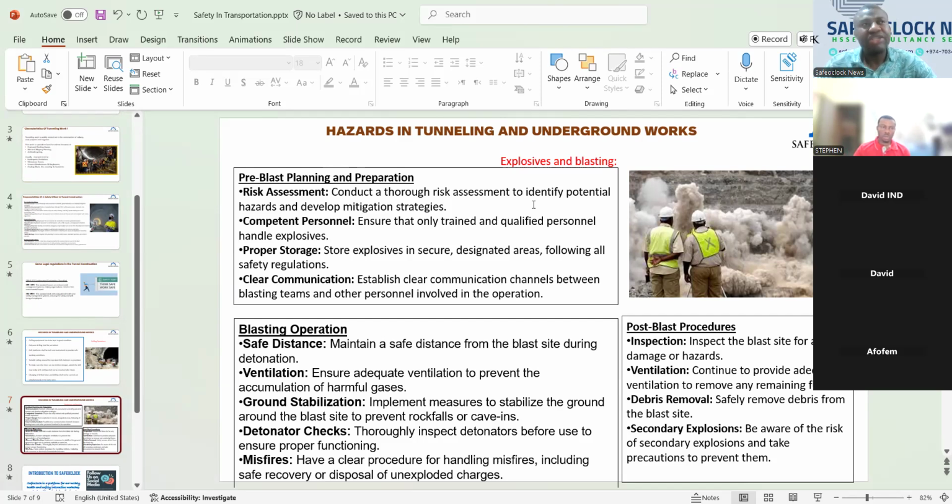Proper storage. When we used the explosive during the construction of Qatar Metro, it was transported directly from where the CID kept these things. So from that location, it comes to the site. Immediately after the blasting, the civil defense team takes it directly with those contractors and removes it immediately from the site. So there is no storage area on the site. You can't store this. It was not allowed to store any atom of that explosive on the site. So proper storage should be maintained.